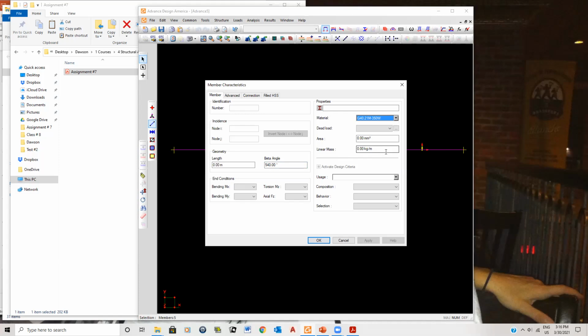That used to be the right steel that when these shapes were being produced in Canada, that was a steel that the Canadian mills were actually producing them to. So use G40.21M-350W. The W stands for weldable steel. The 350 stands for 350 megapascals for the yield strength of the steel.